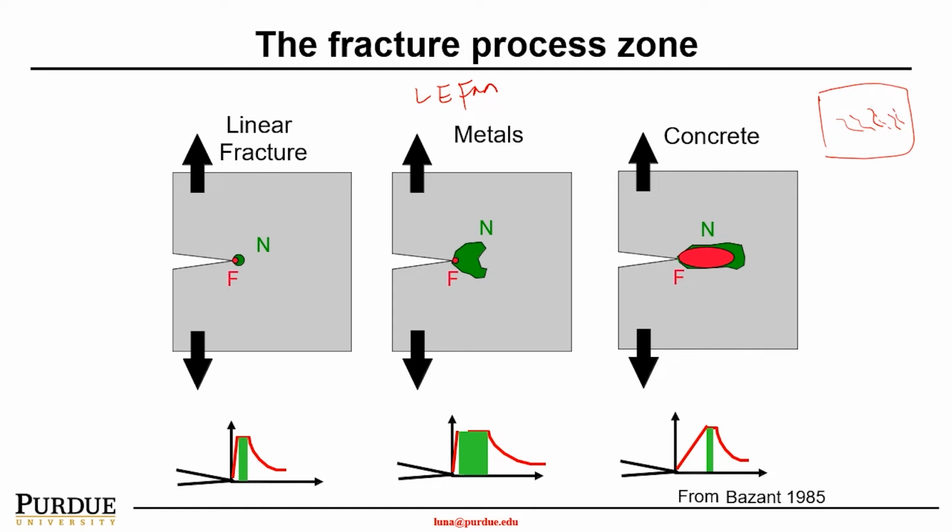When the concrete is under loading and the crack tip propagates, all those small shrinkage cracks may propagate and merge, and then they become a single large crack. And that becomes a single structure that gives continuity to the already existing crack.